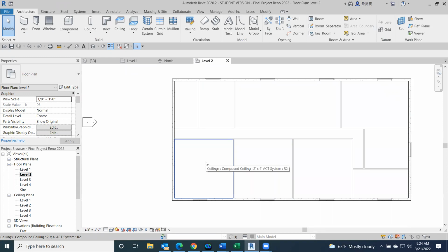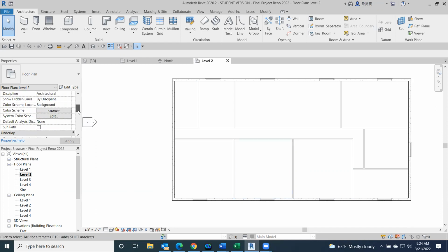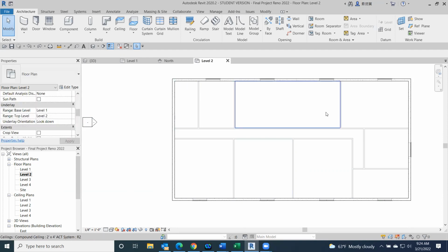It's actually quite useful at the beginning of this, because if you want to lay over your current walls, keep these same walls in the same space and have them go up, have a similar floor plan to each one, it's good to see where those floors are. But sometimes they get a little confusing and people don't like to see that. And especially when we start laying out a multi-story building in our sheets, we don't want to see these floors underneath. So you can change the underlay.